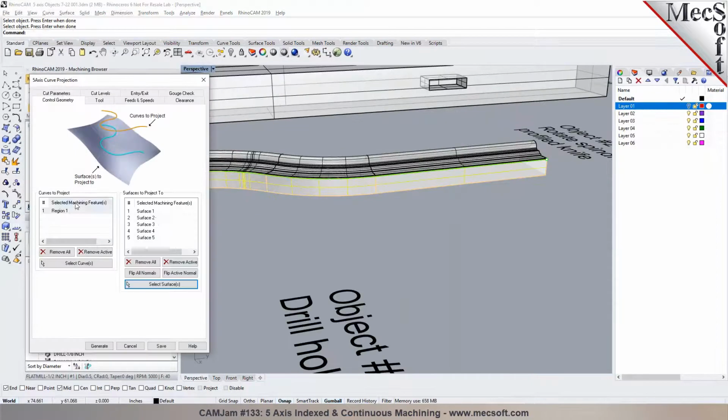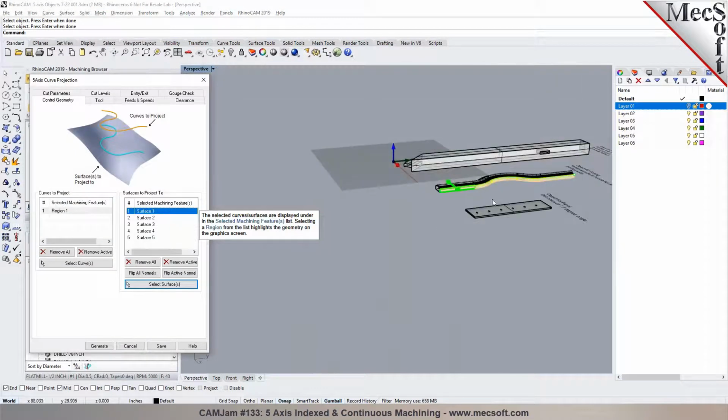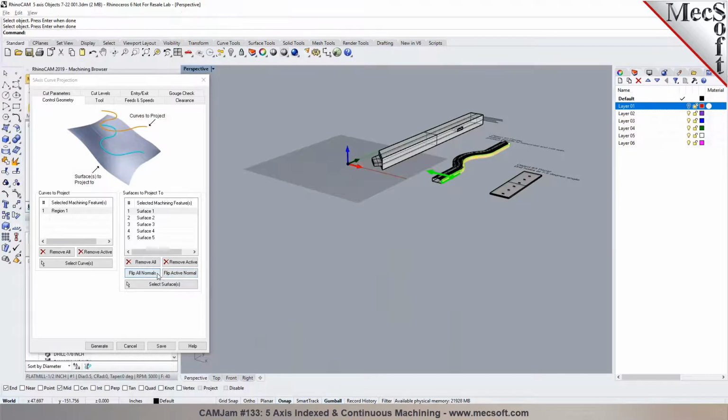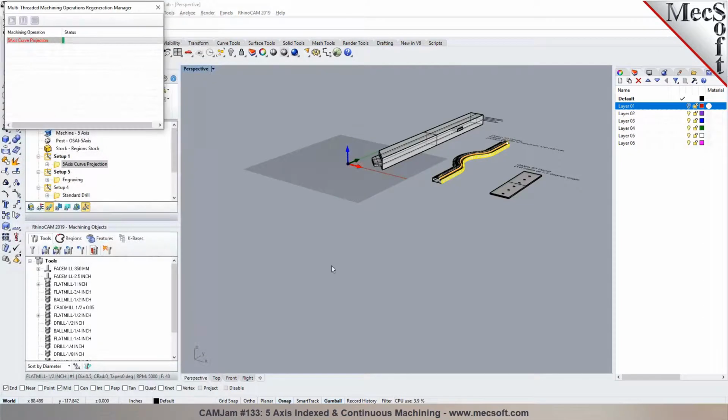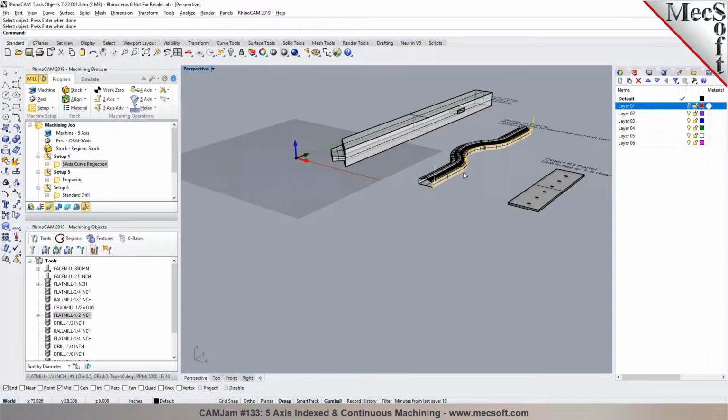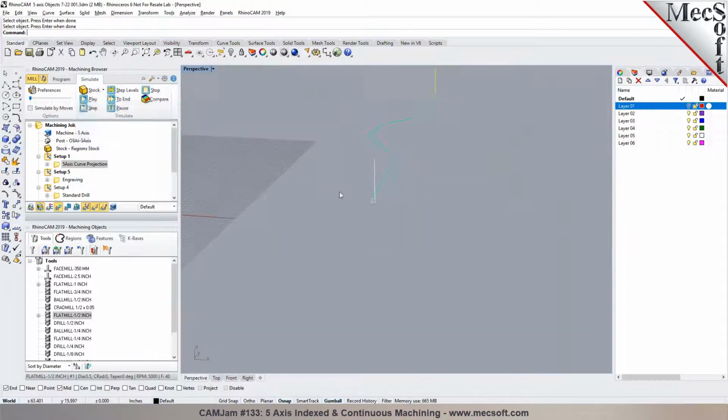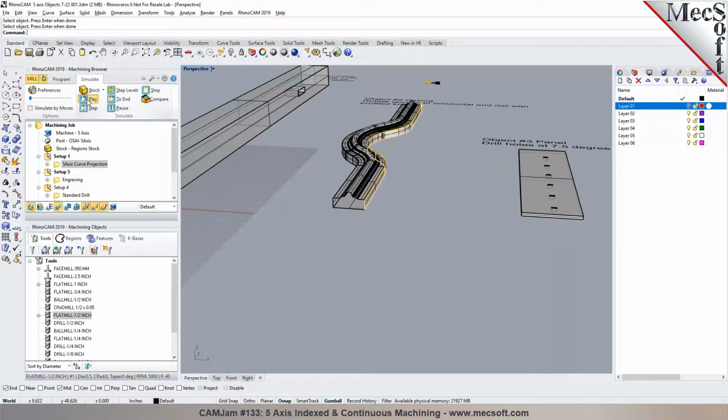So you need to just basically model like a drive surface. Yeah, I see. Tool to be normal too. And now generating this path. You'll notice that the tool is normal to that, and it's actually flipping the angle because it's right over the edge. So I can move this curve slightly below it, and you'll see it basically is normal to that.